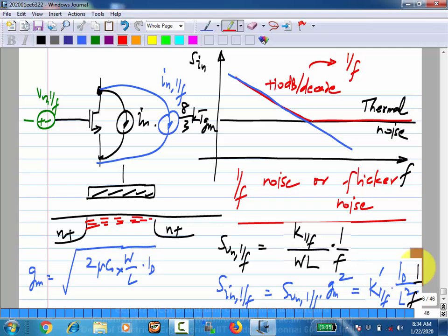Now this again is a trade-off that you will see in more detail in analog IC design, if you are taking it. You always have a trade-off between precision, power dissipation and bandwidth. For high precision you should make everything big. Then if you have two identical devices, they will be matched very well. On the other hand, if you make everything big, the parasitic capacitors will increase. So that means that the circuits will become slower. Also, to charge these parasitic capacitors at a given rate, you will need higher currents, so you may have to increase the power dissipation. So these are contradicting trade-offs that you will have to fight with.